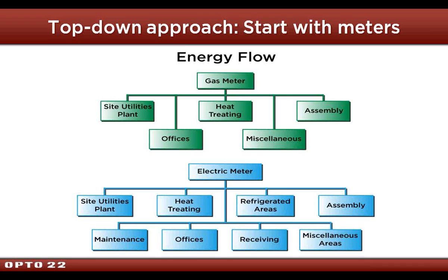Energy management or other systems, they start at the bottom, all the points they need for control, temperatures, and then they build upward. And when you do that, it's very expensive because you have to buy all that instrumentation. Remember, I was buying it myself. So if you start at the main points and the main meters and you get the main loads, then the software in the computer can do the calculations, subtraction. You don't have to monitor everything.